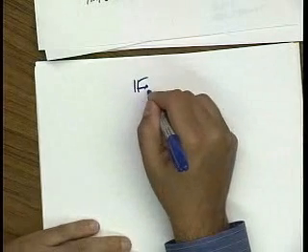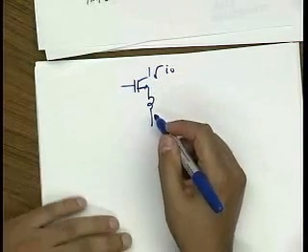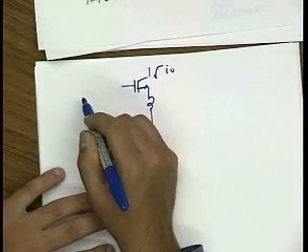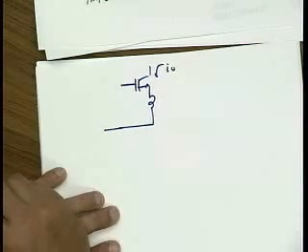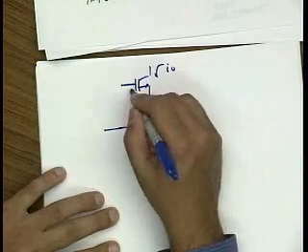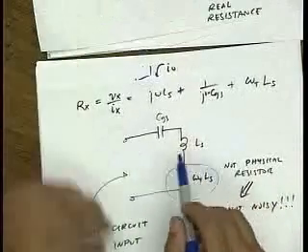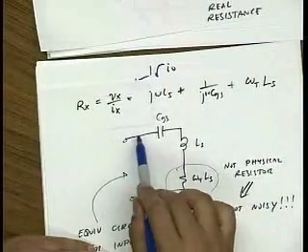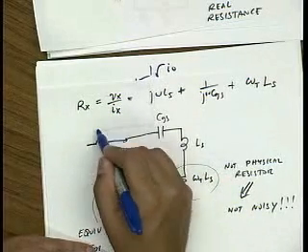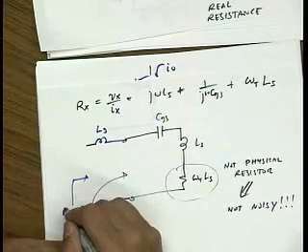Okay, so let's look at the current gain of the degenerated device. Call this I out. Let me just calculate the current gain that I would see. And what I'd like to do is now form a full resonance. So coming back here, this does not necessarily resonate at the frequency of interest, right? So I could just add some inductance in series here, call this LG, and now move the resonance frequency, make this resonate at omega naught.